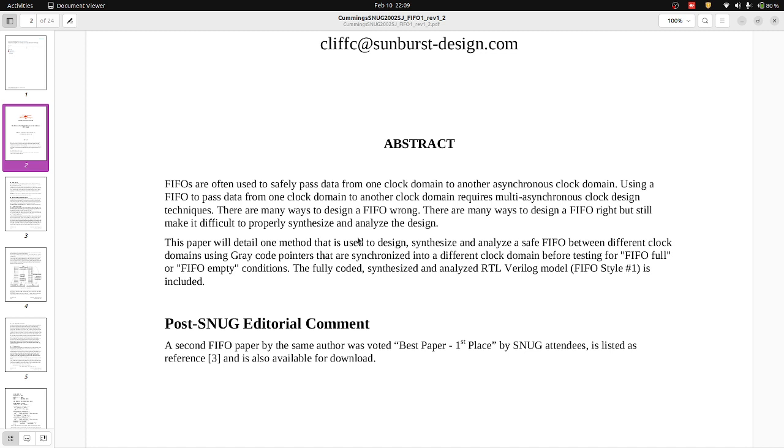So what we will do is start storing the fast data from the fast clock domain into a FIFO buffer with the faster clock, and with a slower clock we will read that data. Whatever data is left in the burst size will be used by the read clock to read it again, even after the write clock, which is the faster clock, has stopped writing the data. So that's basically why we need FIFO.